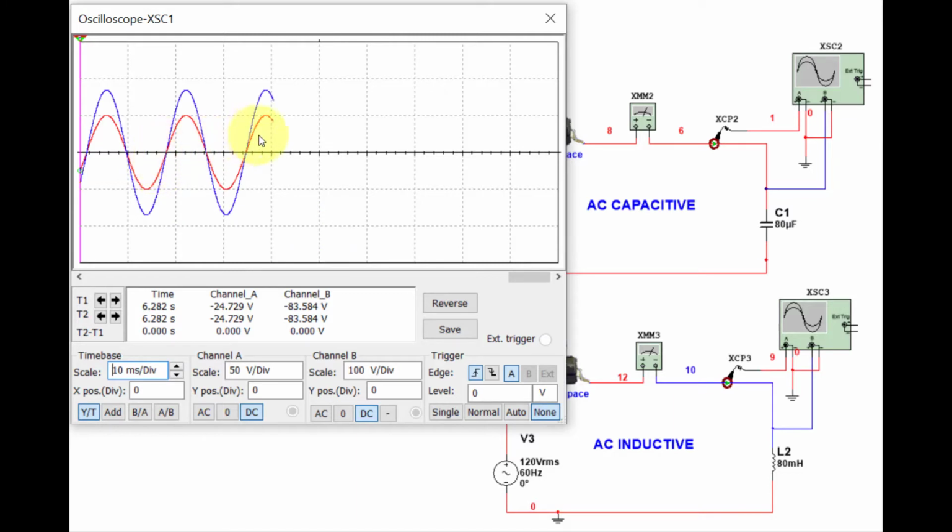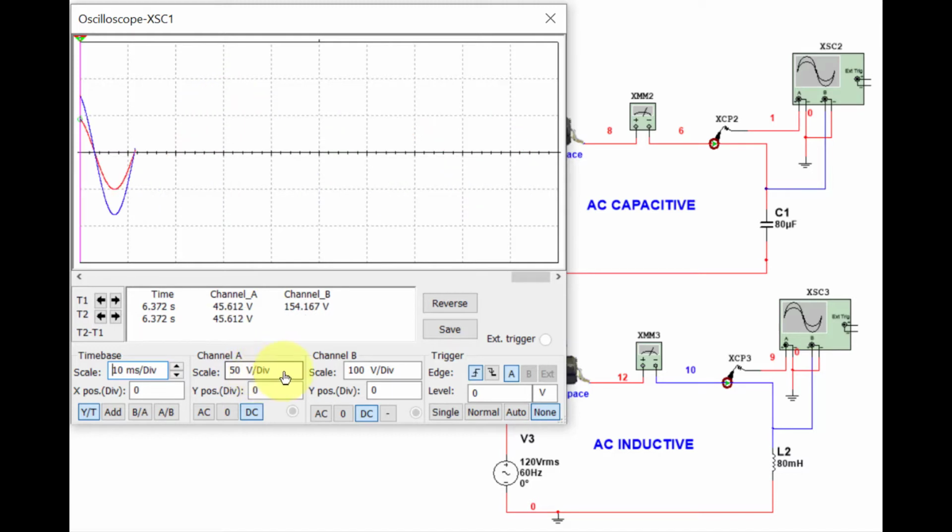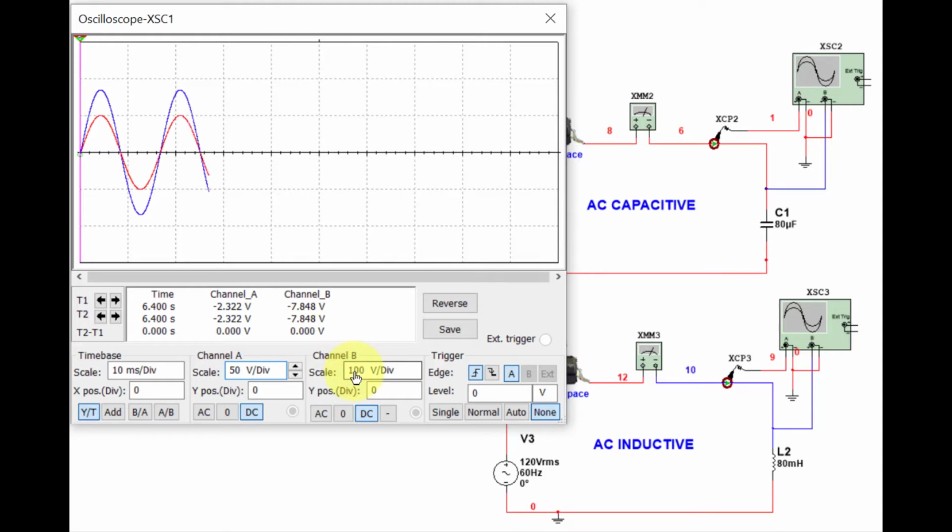Now, on a vertical scale of an oscilloscope, so this is part of our review, the vertical scale or the y-axis, you are looking at signal level, and it's represented by volts per division. If you want to change the scaling, down here you adjust that level by changing the volts per division. And channel A and channel B are independent of each other. So you can look at 2 different traces.